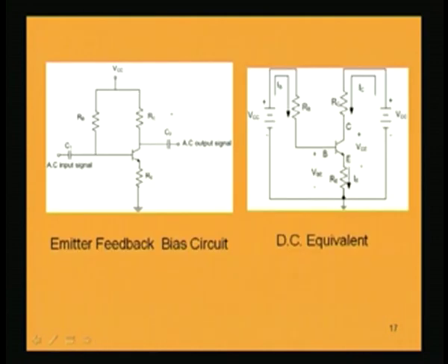In this circuit also, if we consider the DC equivalent circuit only, that means when DC conditions prevail, the capacitors C1 and C2 will be open circuits at these two points. So, we will be left with this DC circuit without these capacitors, and again I am separating out these two VCC sources just for easy understanding, nothing else than that, and then I can analyze the circuit separately.